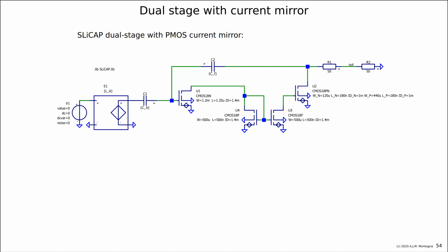So at this stage, we are focusing on feasibility, on rough numbers, indications. Is it a good solution, or can another solution really be a lot better than this? That is how we are building up the design, doing structured electronic design. And that's why we need SLIDECAP. Because now, for example, you could even sweep the operating current of the output stage and see what it does with the pole-zero pattern.